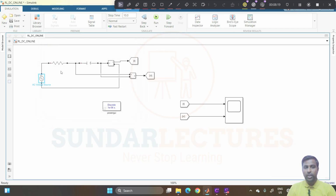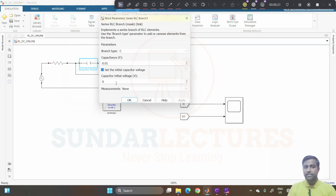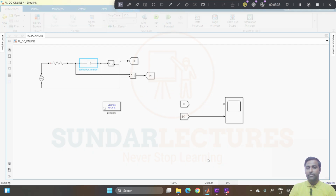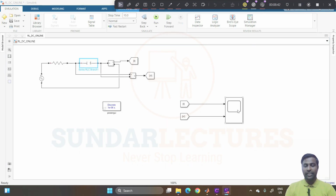You just click OK and change the R value to 100 ohms and the C value to 0.01, and set the initial voltage to be 0 volt, right? Then give OK, and then you just run this one. If you run this, after completing 100%, you can see that. Now that's all, it is completed.